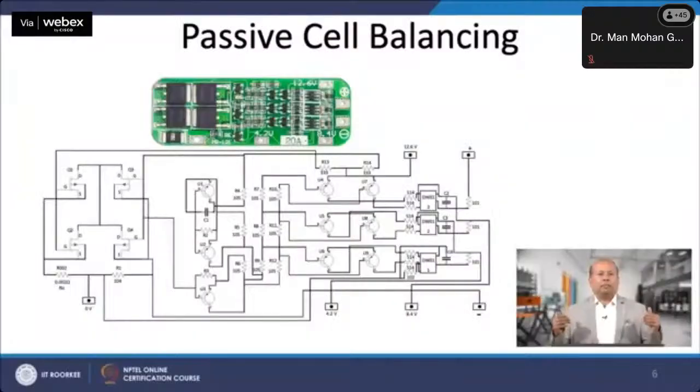Let us observe the charging operation. The battery module is charged by the DC power supply, and the path of the charging goes through the DW01 protection IC, and through that, switching MOSFETs 1 and 2.